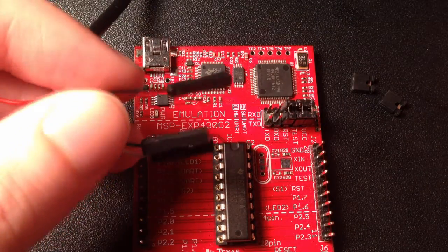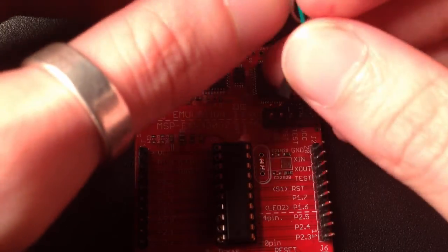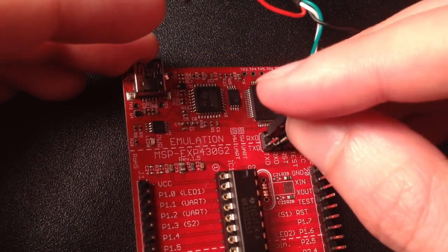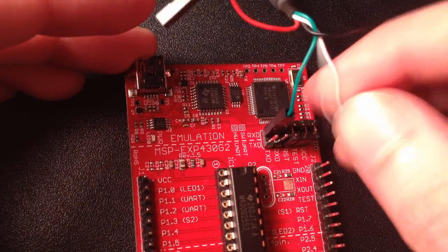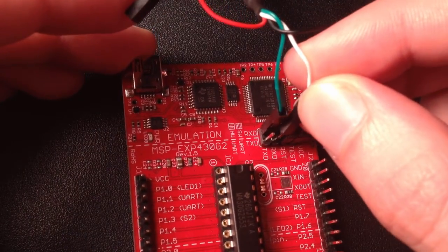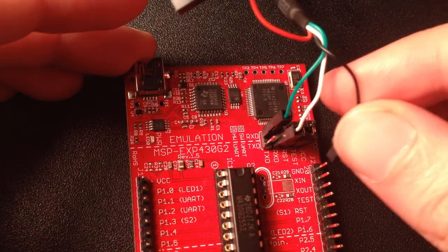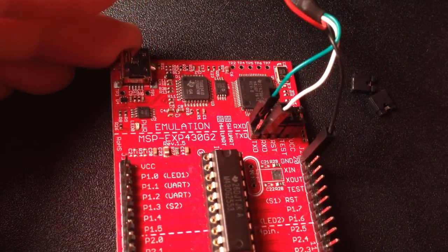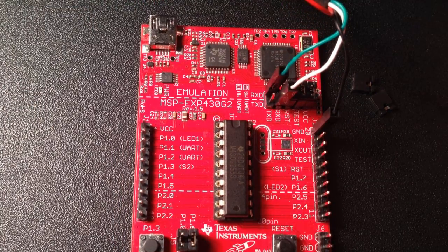And for this, we'll only be using the black, green, and white wires. The green transmit wire will need to go at the pin on the upper left of the block. The white one will go at the bottom right of the exposed pins. And then finally the black ground wire will need to connect to the ground pin there at the top of the second jumper block. And then you're all set. You'll need to connect the USB end into your machine.